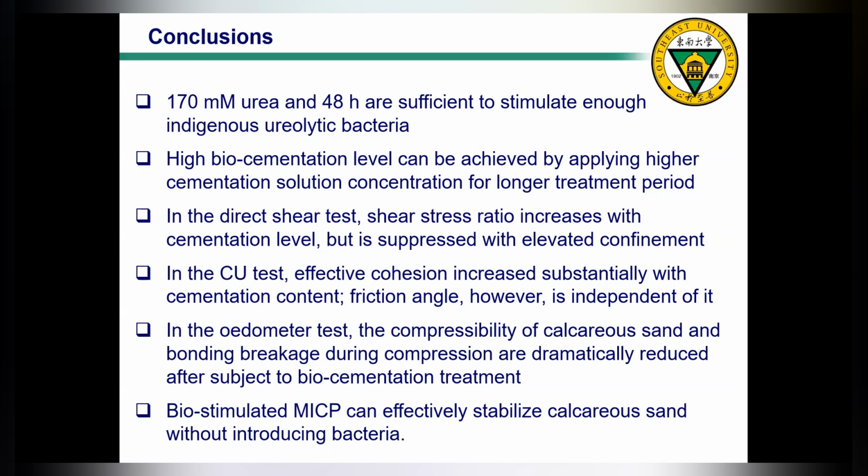Thirdly, in the direct shear test, the peak shear stress ratio increases with cementation level, but is suppressed with elevated confinement. Then in the CU triaxial shear test, effective cohesion increased substantially with cementation content. Friction angle, however, is independent of it. Then in the oedometer test, the compressibility of calcareous sand and the bonding breakage during compression are dramatically reduced after bio-cementation treatment.